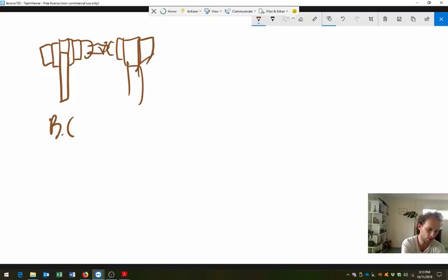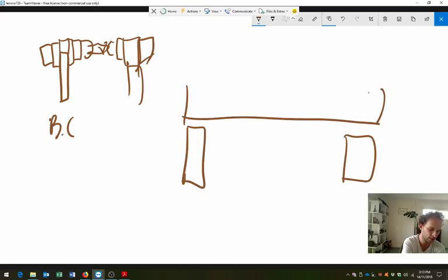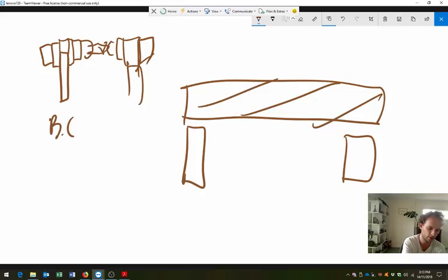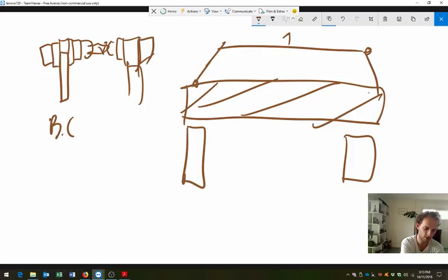Great. So whole span precast, if we've got a pier here and a pier here, we just lift in the entire section with the crane in one lift. So that's span by span. We lift in a whole span. So that's obviously heaps faster, but we've got huge weights to lift, and we also have to transport this thing to site, which isn't that easy.